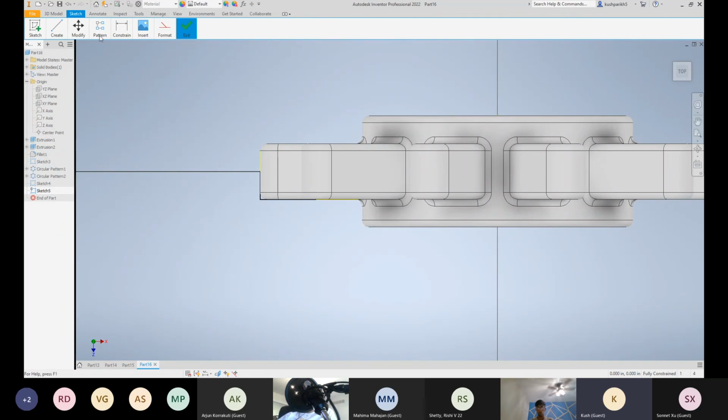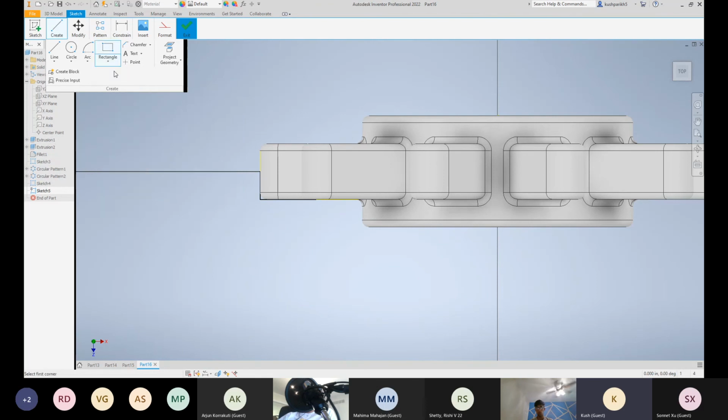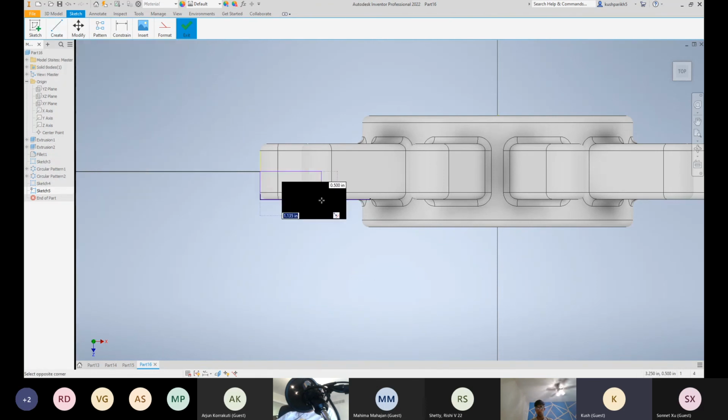Now all I want to do is create my rectangle. So I go create rectangle. For this instance, I want to use a 2-point rectangle since it's a bit more convenient. I press that, and I just select where I want to start and end, maybe right around there, like that seems good. Right now you won't actually see where the rectangle is, and that's because it's inside the protrusion. But you can just imagine there's a rectangle that you already made over here. You can see the green outlines.